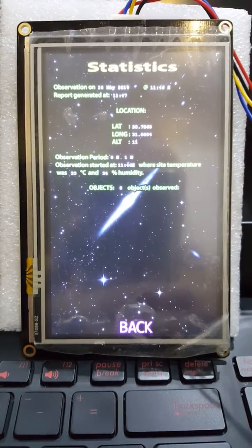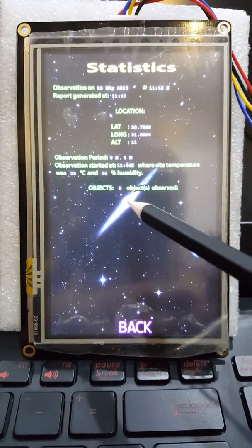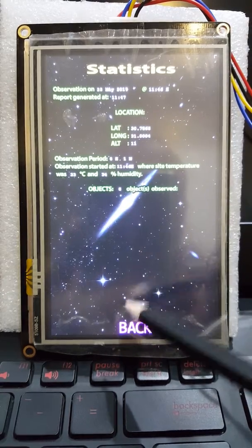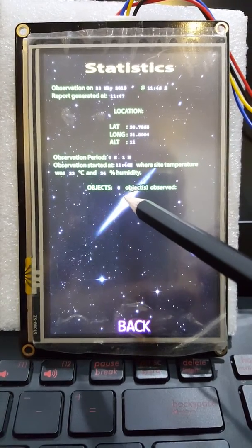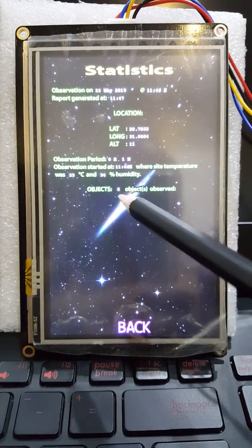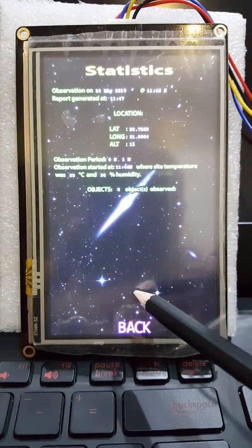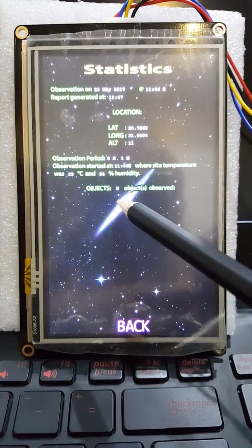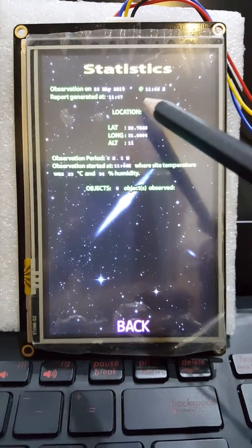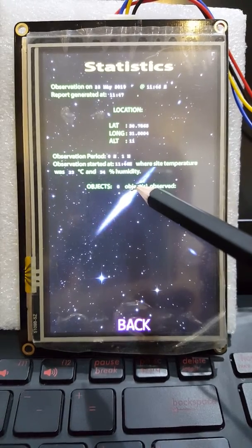On the serial monitor and the old screen, it's able to print the names in lines. But in this case, if you look back into the design page of this screen, I have only one text box, and the maximum text characters in the Nextion is only 254.